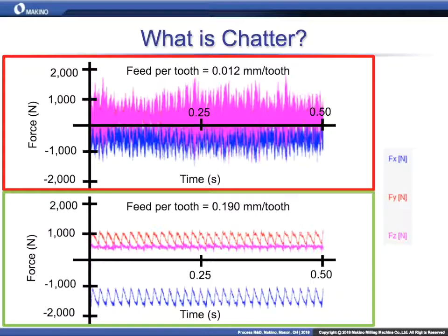You can elastically deform your workpiece if you have a small enough feed per tooth, so that after the tooth finishes trying to shear away a chip, you haven't done anything. It's just rubbed on the material. And what can happen is, let's say one tooth fails to shear a chip, it only rubs, and the second tooth fails to shear off a chip, and it just rubs. Well, now the third tooth has to take 3 times the expected cut because the first 2 didn't cut anything. So you can see where you have a miss cut.